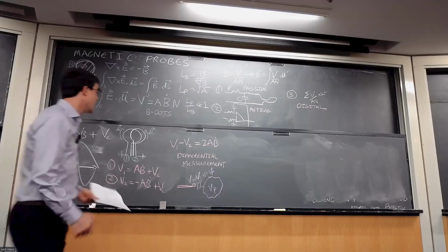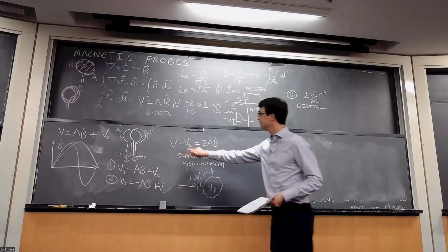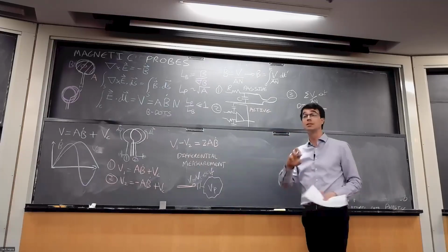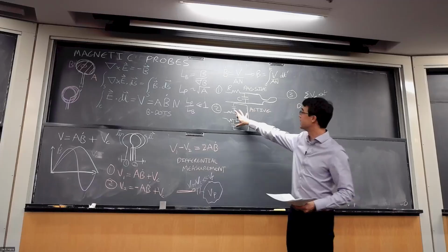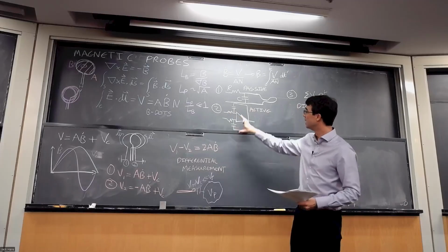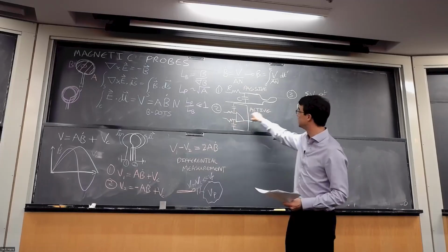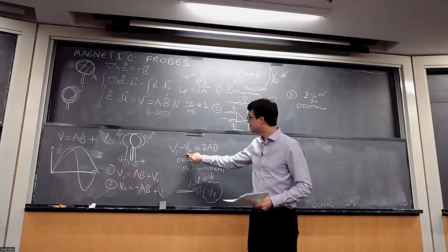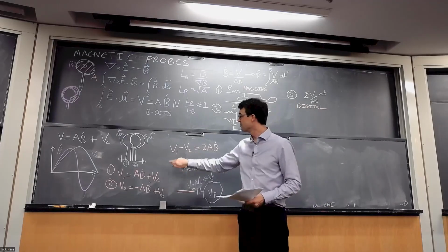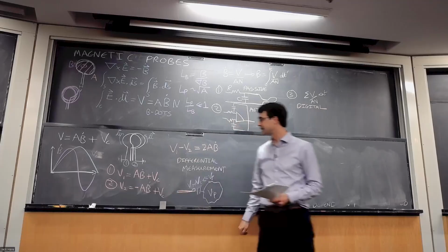Okay, I'm going to move on. So just to say, you can take these two signals here and you could feed them automatically into an op-amp similar to this, and you can make an op-amp circuit that does subtraction, and then you could feed that into an op-amp circuit which does integration. The trouble is, unless you inspect these two signals visually, you may find that one of them is more affected by the capacitive coupling than the other.